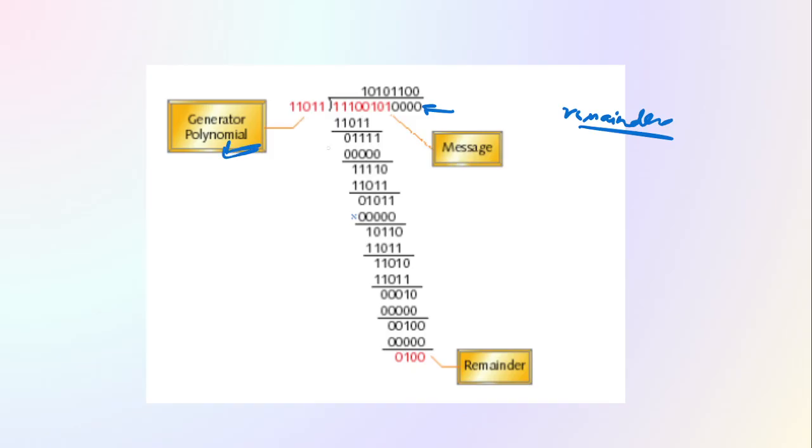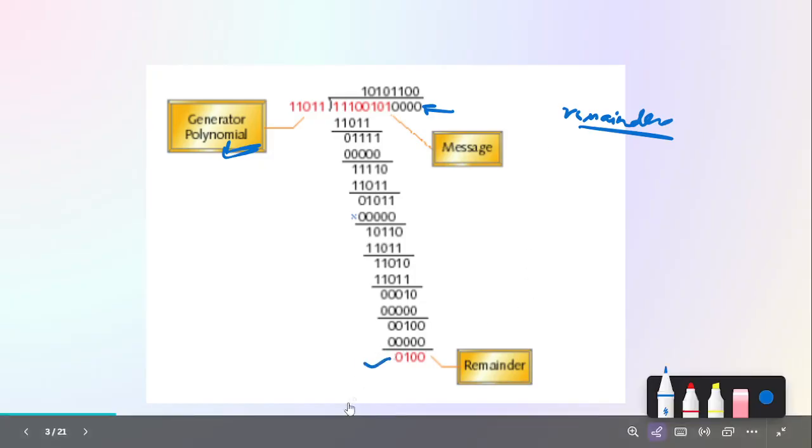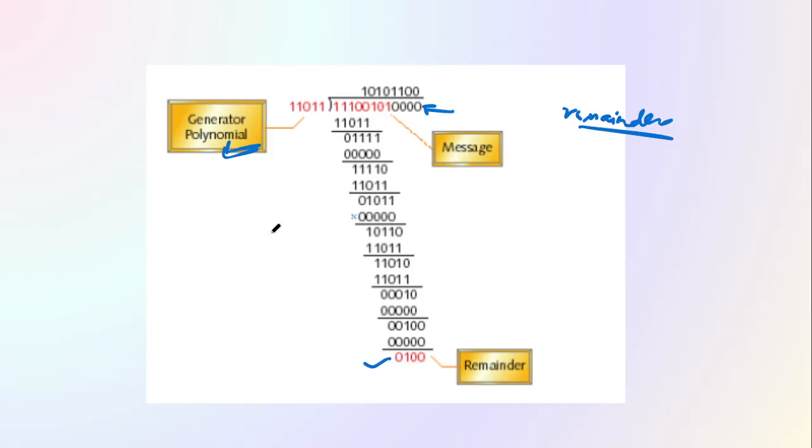The subtle difference is that if you were to just do a simple division in math and stick the remainder at the bottom as your CRC, you won't be wrong. But the way traditional CRC is computed, it is computed over something called a binary Galois field, and instead of using real division math, we use what is called XOR math.